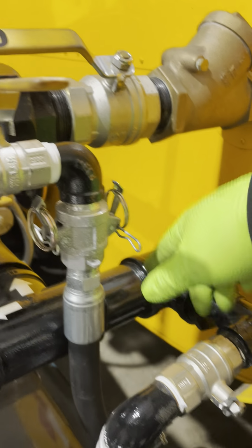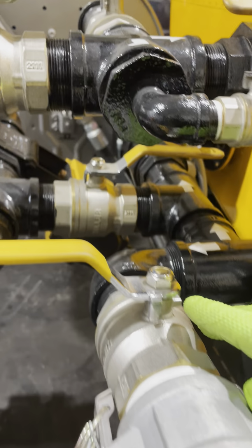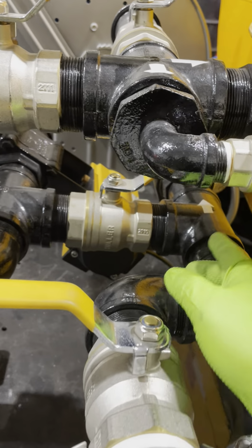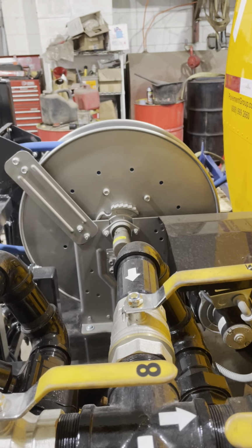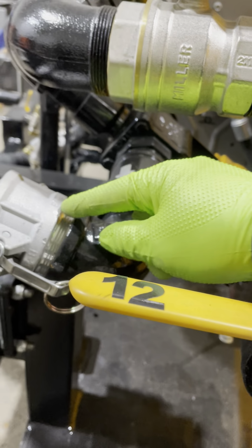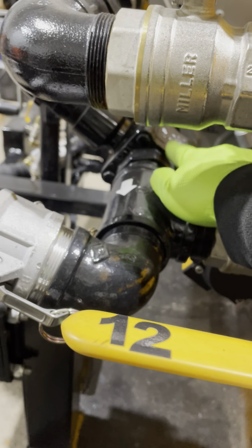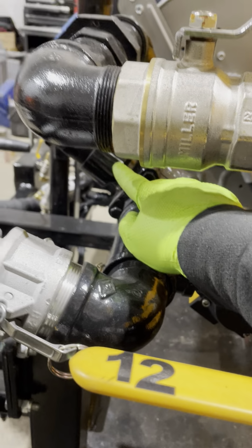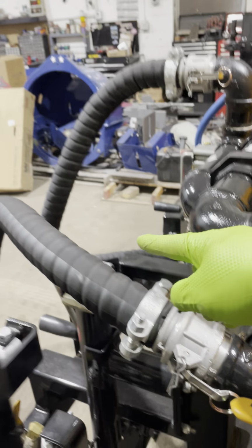Coming into the manifold, off. This is off, nowhere to go. It comes up here. Up top is off, that's nowhere to go. So it's got to go this way. It's going to follow 6. It's going to come off to the left because it's got nowhere to go here on valve 7 until it gets around to the other hose. So it's going to follow this route.